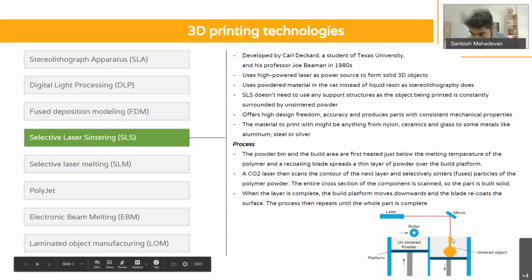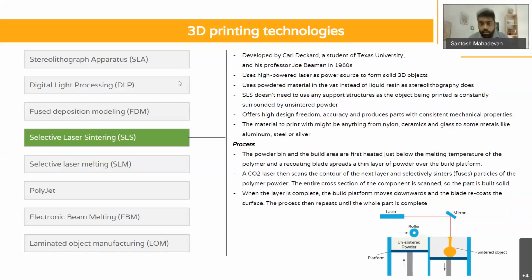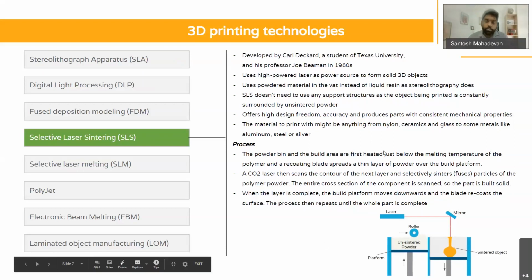So if you can see this small extension over here, or this extension over here, there is a certain degree up to which these methods will not require supports, because each layer is able to form a draft or an angle up to which it can, to an extent, support the cantilever. But if the angle is too extreme, typically less than 30 degrees to the horizontal, 20 or 30 degrees to the horizontal, those kinds of parts require a support. And in the case of SLS, you require no supports whatsoever.